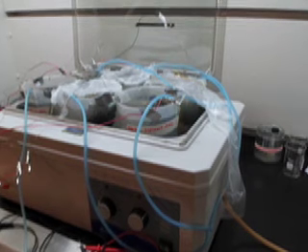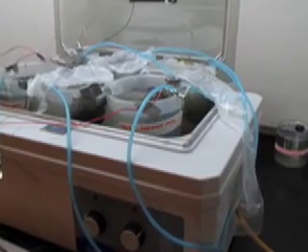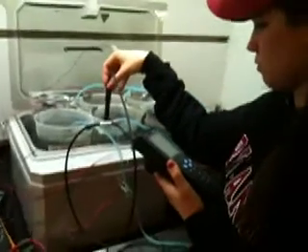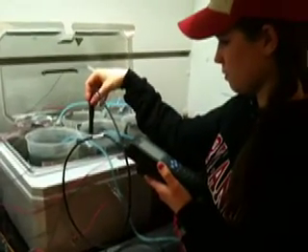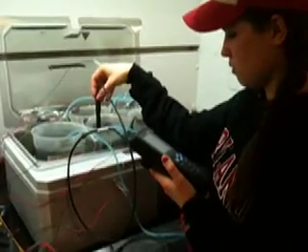We must ensure that there is an ample amount of oxygen present in the beakers in order to absorb electrons from the cathode. We also must consider that aerobic microbes throughout the water will be consuming oxygen, so measuring the dissolved oxygen in each cell and providing proper aeration is important.